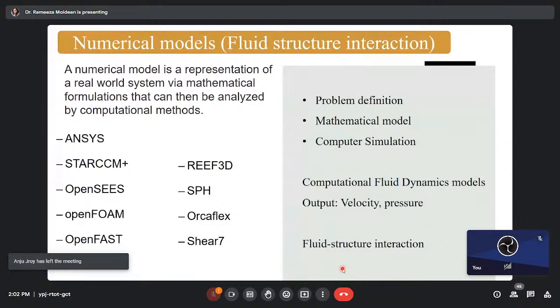But before that, there are two software, OrcaFlex and SHEAR7, mainly for studying vortex induced vibration in cables. OrcaFlex is even being used by the industry. It is a commercial software, but it does not actually model the different materials which make up the cable. It introduces some factors for considering the different materials in the cable. So it is non-homogeneous, but it considers it homogeneous and then gives a factor to adapt to the fact that it is made of different materials.